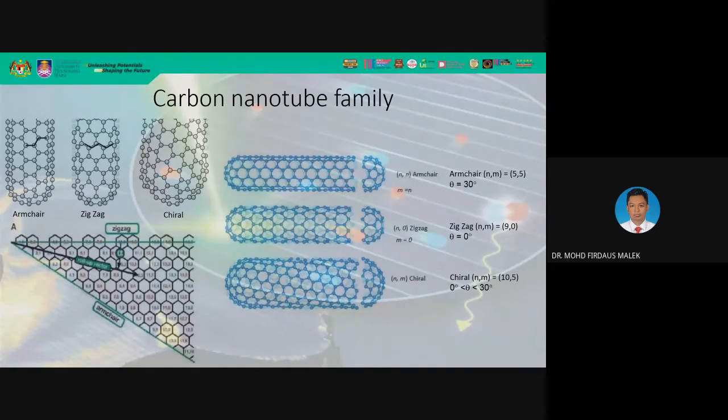Okay, so this combination or composite is called functionalization, which I have mentioned in the previous slide. So taking this bonding together, if the molecule attached to the carbon nanotubes is also attached to carbon fibers, these functionalized carbon nanotubes can bond to the fibers in the composite, producing a stronger material.